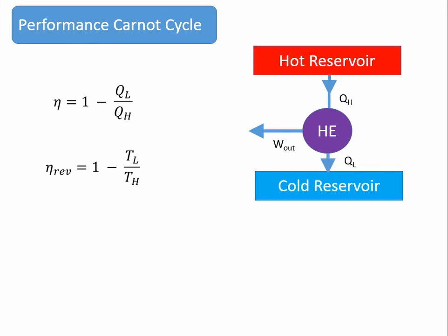The cold reservoir, on the other hand, is constrained by the room temperature, because we are taking either seawater or river water or water from a tank to cool the condenser cooling fluid. Therefore, the temperature of the sea or the river or the tank, which is the room temperature, determines the lowest temperature, TL.